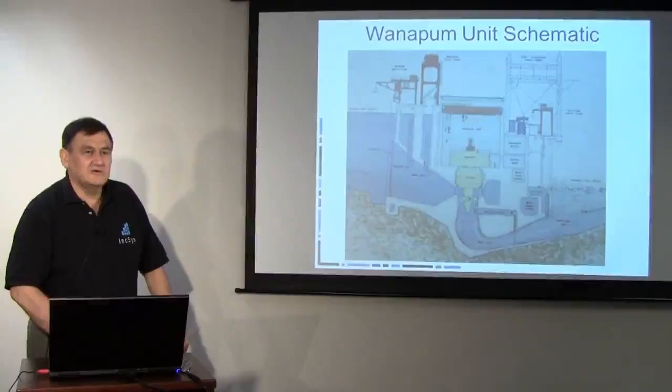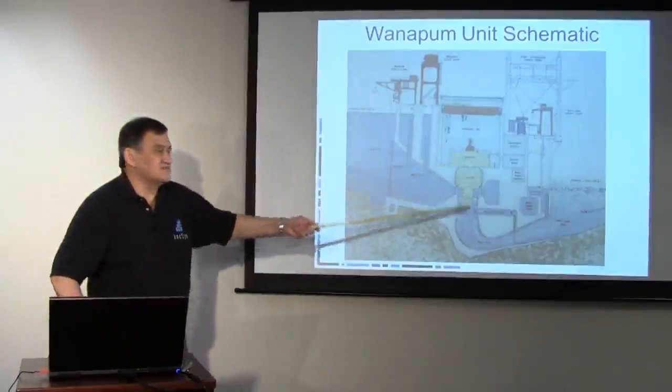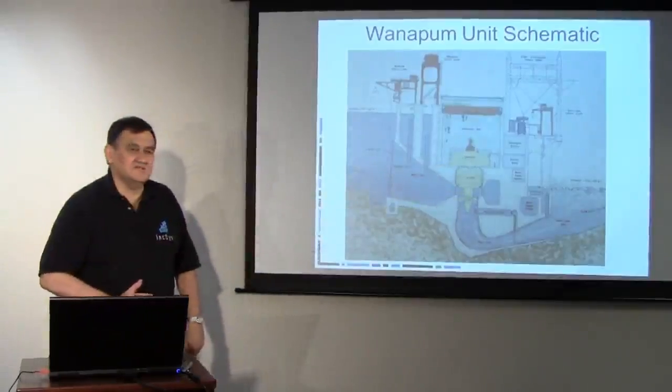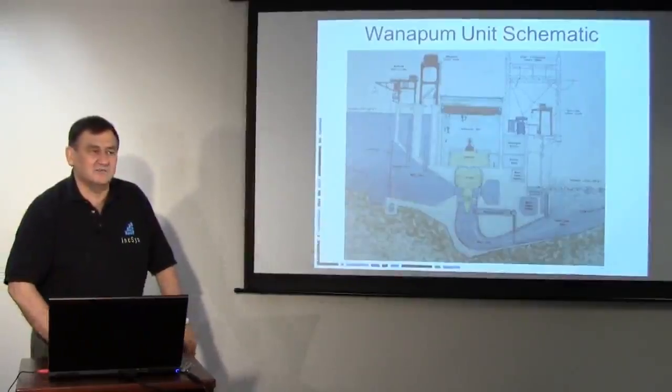In taking a tour of this power plant, the plant operator, Bob Jordan, said that if there was a really desperate situation, say there was leakage coming into the plant due to an earthquake and there was no backup diesel available, he would actually start the turbine and suffer the damage to that thrust bearing, because that action could save the power plant. So that's an example where under extreme conditions it's okay to break some of the rules, realizing that you'll suffer a little bit of damage versus losing an entire power plant. I thought that was a fairly innovative example of thinking through the different contingencies.